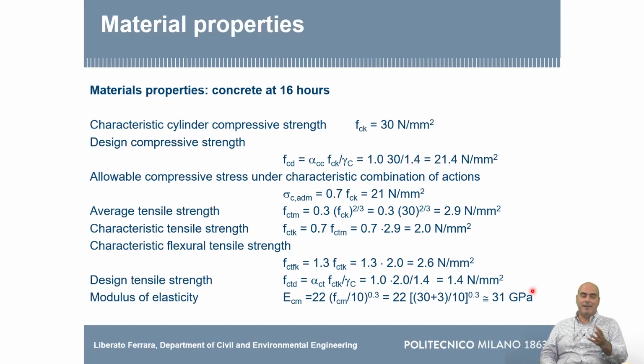Because there are some formulas we have seen. The maturity-based method is for your own check to decide whether it's good enough. For example, if it's not exactly 16, but it's 14, or if you need to go a little bit more. But the maturity check is for internal control, but has no legal validity. To have that, you must have the tests, and you must keep the logbooks for these tests.